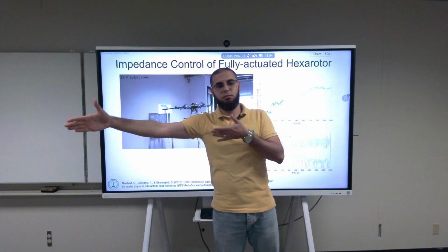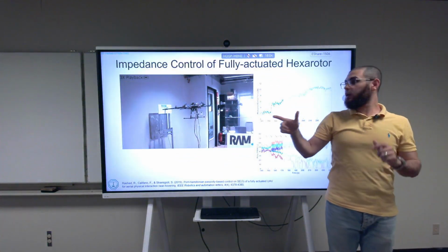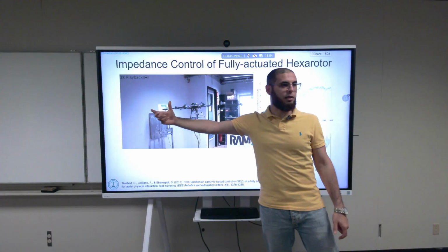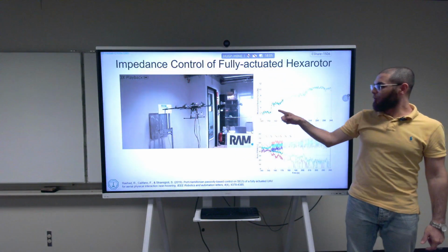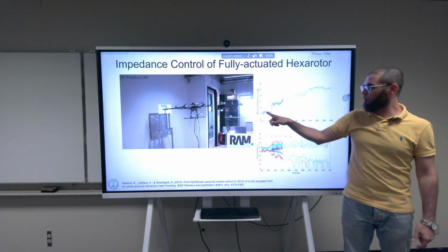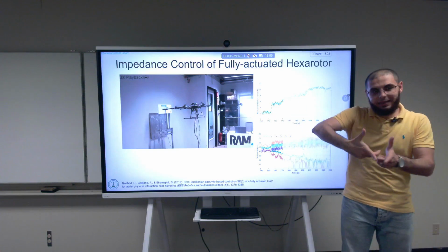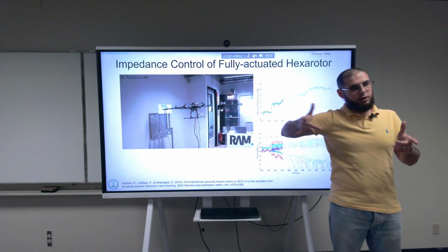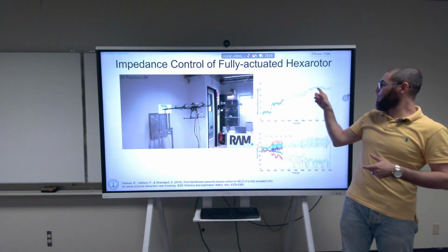So what does it do? It pushes on the wall. Behind this wall, there's a force and torque sensor. We put it there, and we're measuring the force it's applying. You see it already got in contact. Earlier we were measuring 2, so it was already pushing, and then we take the virtual desired point more inside of the wall. We're pulling the spring more and more, so it's applying more force.